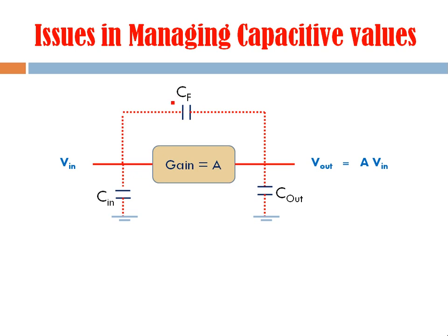So if we have to include this capacitive component into the analysis, then we have to do this AC analysis at both nodes, here and here. It's not that it is difficult, but it adds some more processing steps, and that way the inclusion of this feedback capacitance into our calculation becomes more tricky.